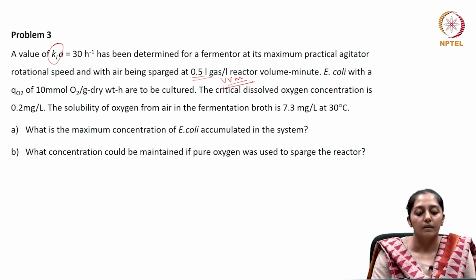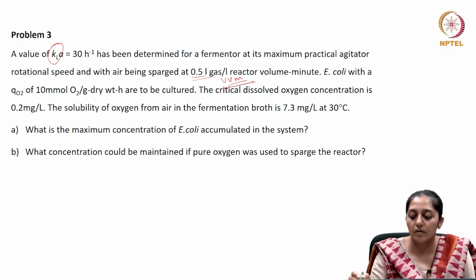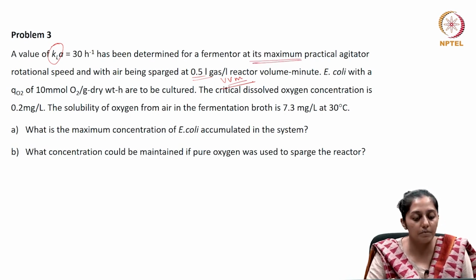So, the volumetric mass transfer coefficient under the operating conditions of maximum possible agitator speed and 0.5 VVM of air sparging rate is 30 hour inverse.